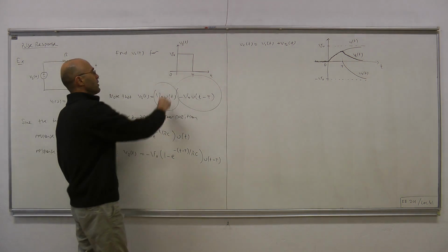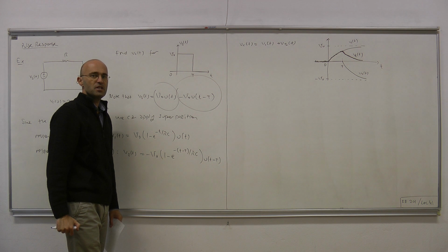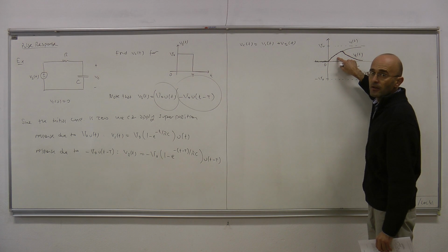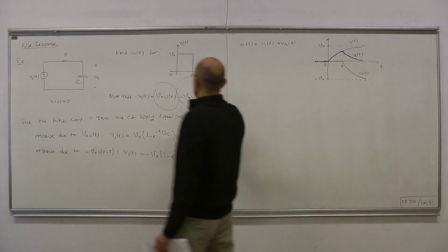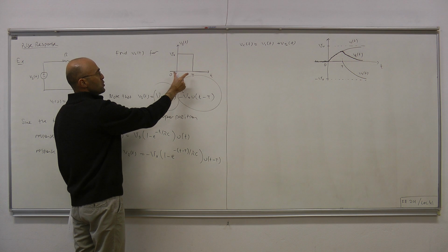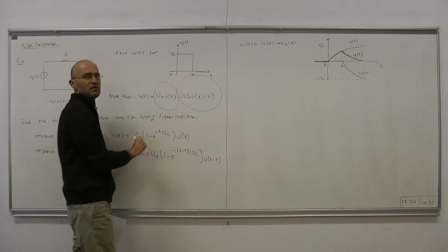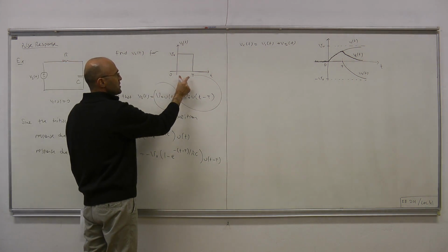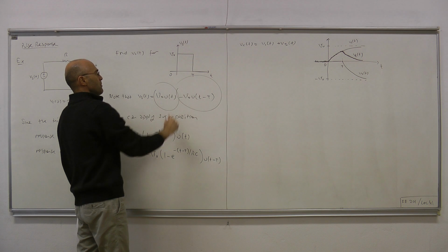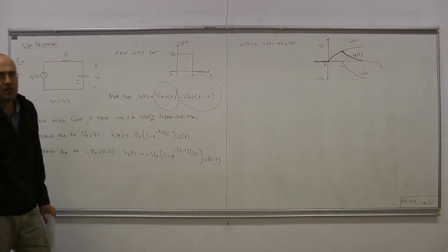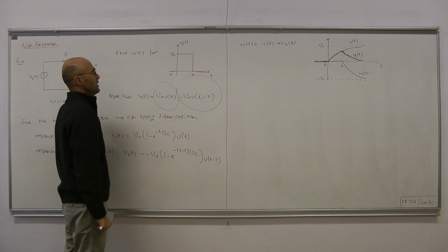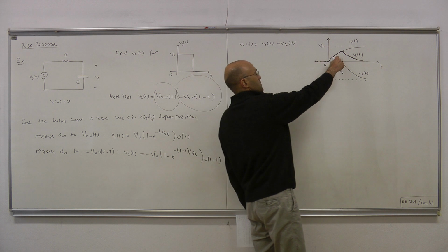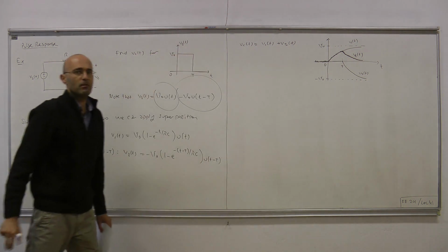So we're going to pick V0 to equal 1 over T. Then we obtain this curve and see what happens to the response as you squeeze capital T further and further. Since the area must remain constant at 1, as you squeeze this interval, the height must increase so that the area is kept constant. And then in the limit, the pulse response will give us the impulse response.